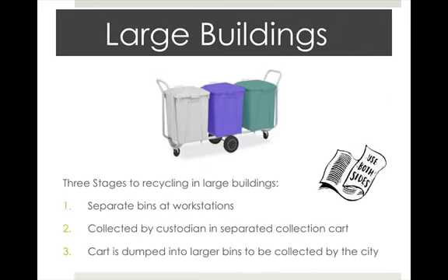So some of this pertains to you as an interior designer, but other parts of it are just for your information. Now, garbage bins located on the grounds of large buildings should be fenced to keep out animals and pests, and include recycling bins and possibly a compost pile for the landscaping. They should also allow easy access to the garbage trucks and consider the wind direction and noise control.